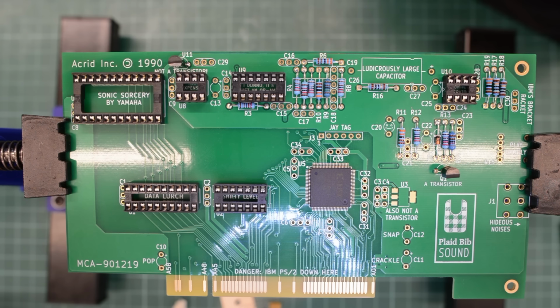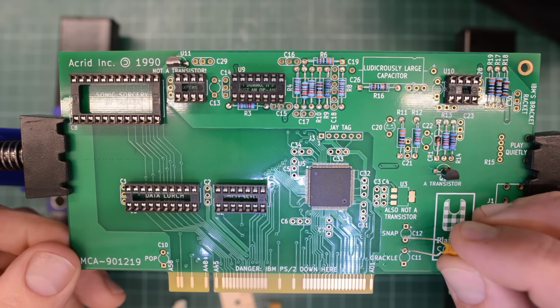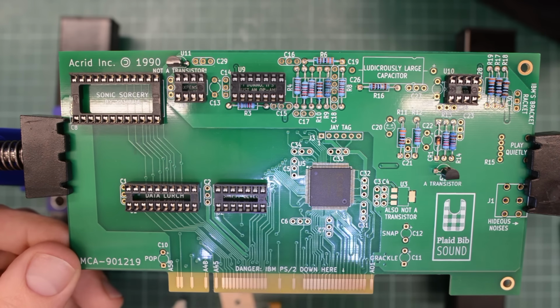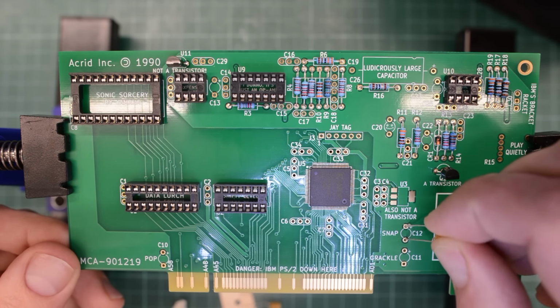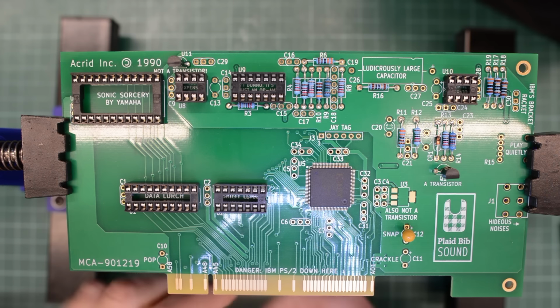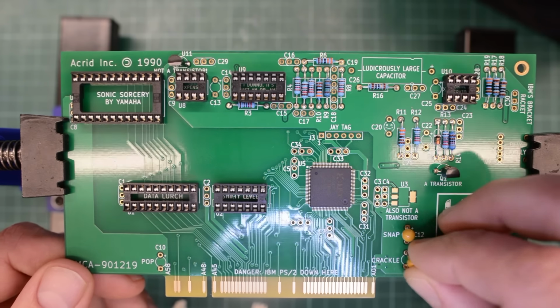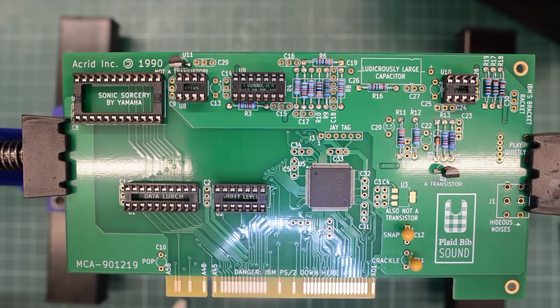Okay, this is moving along quite quickly. Time to put some caps in. And some of these are tantalums. And they are labeled Snap, Crackle and Pop. So I think I'm gonna skip ahead a bit here and install all the caps. The important thing with tantalums is to make sure that the polarity is correct. Otherwise they are indeed going to snap, crackle and pop.